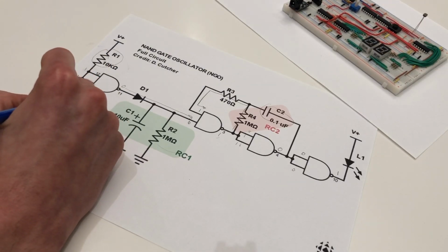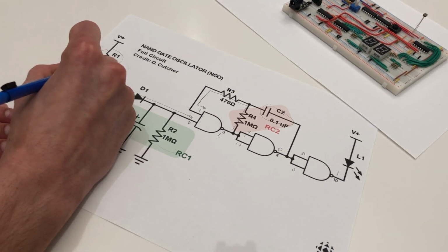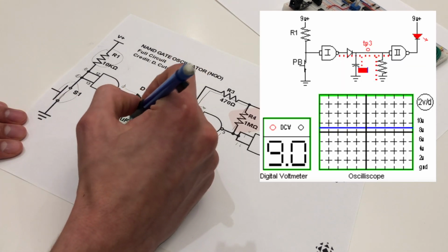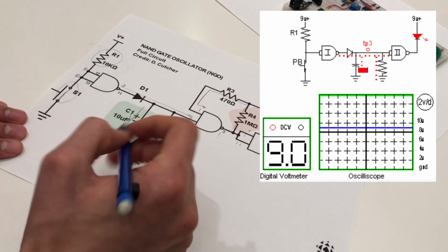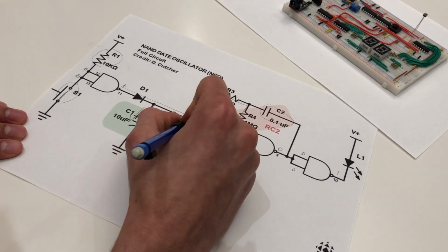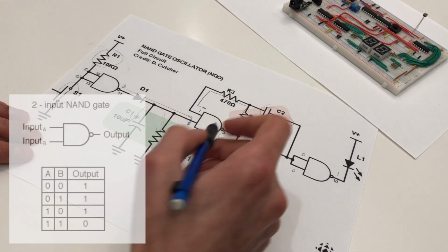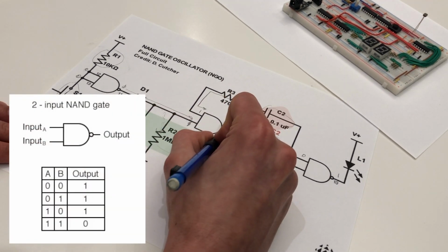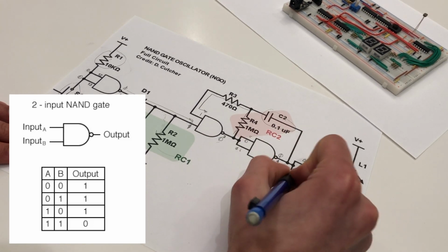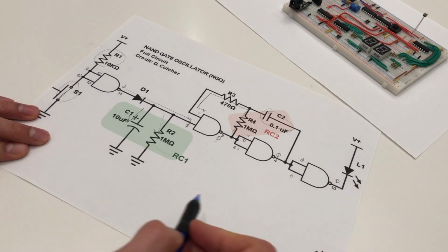When the button is pressed, the inputs of the first NAND gate have a direct path to ground, so they'll both become low, making the output high. Now this capacitor charges instantly because there's no resistance, and some of the current trickles down into R2. This high signal carries on to pin 1, and now since there are two high signals, this makes low, low, low, high, high, high, and low. This makes the LED turn on because now it has a path to ground.